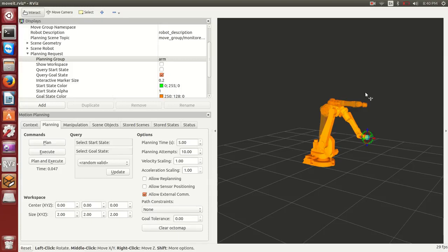If you've ever done kinematics, we know that inverse kinematics is much more of a pain. That's why you rarely see robots above 6 degrees of freedom, because the kinematics becomes very difficult. Here I'm pivoting around a point. I can't really tell, maybe that's pitch or something.